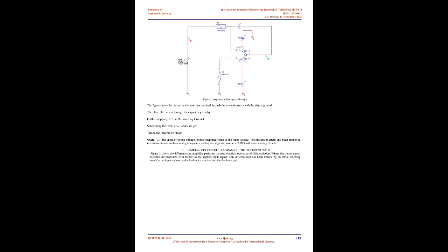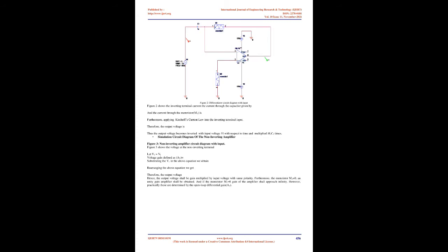and implemented using a thin film of titanium dioxide. In this work the design and analysis covers all the basic analog circuits. These basic analog circuits find varied applications such as oscillators, active filters, PLL, and encrypting data. This paper utilizes the simulated Memristor device in an analog circuit. The Memristor was implemented in OrCAD-PSPICE and the switching condition was verified. OrCAD-PSPICE 16.0 is used as the simulation tool.